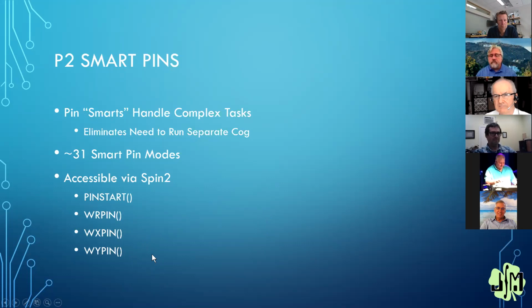Now, some of the smart pins take a little bit of effort to set up, but a lot of us are writing objects, so that will be kind of compartmentalized and you won't have to worry about the gory details that I'm about to show you. But within Spin2, there's pinstart, wrpin, wxpin, and wypin that lets you do all the details of a smart pin, just like John showed in assembly last week.